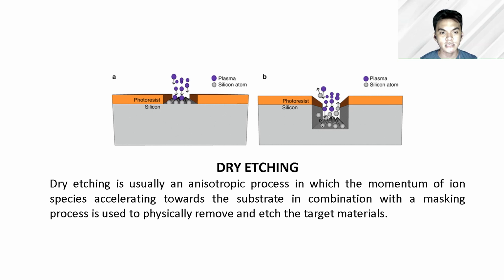The second method is physical sputtering. That is, ions in the plasma are used to strike and remove excess oxide layer. As an anisotropic etching method, it has different etching speeds in the horizontal and vertical direction. So its fineness must exceed that of chemical etching. However, the disadvantage of this method is that the etching speed is slow because it completely relies on the physical reaction caused by ion collision.